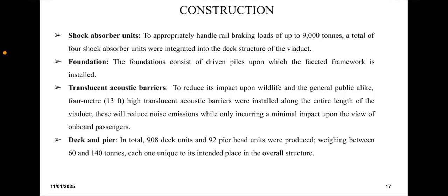Moving on to the construction of the Colne Valley Viaduct. The first is shock absorber units. To appropriately handle rail braking loads of up to 9,000 tons, a total of 4 shock absorber units were integrated into the deck structure of the viaduct.